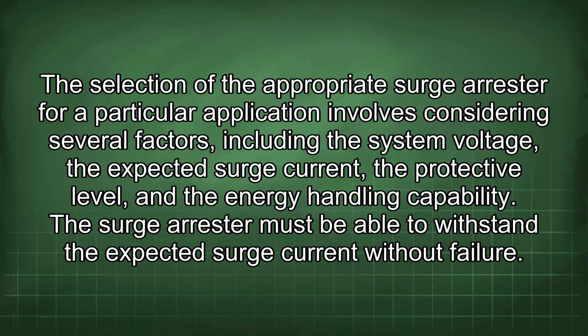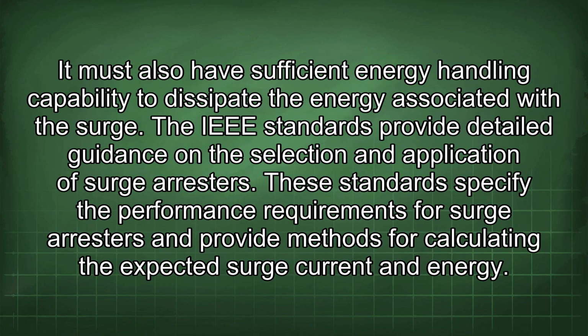The selection of the appropriate surge arrester for a particular application involves considering several factors, including the system voltage, the expected surge current, the protective level, and the energy handling capability. The surge arrester must be able to withstand the expected surge current without failure. It must also have sufficient energy handling capability to dissipate the energy associated with the surge.